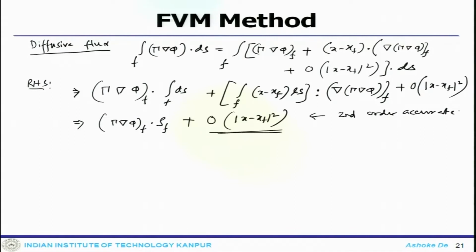So, that means if you use this particular approach and discretize the system, essentially the generic finite volume discretization gives you back all the convective diffusive terms as second order accurate. One can always achieve higher order accuracy. In that case, a higher order approximation you have to use.